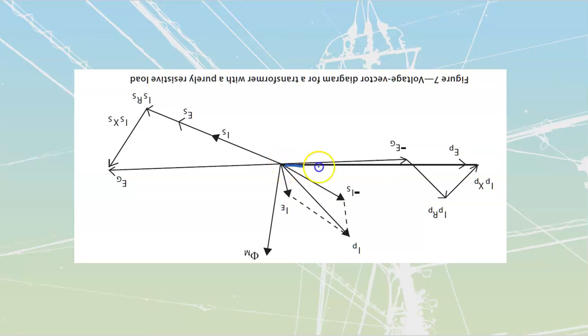And if we look all the way down over here, I'm going to see my applied voltage, which is this one over here. I'm going to see my secondary value of voltage. Now, they start drawing this one off the angle over here because they're starting to apply a bunch of other smaller drops that are going to be inside of here, IX and LS. But most importantly, what we see is we're going to have our secondary current, and then our primary current, which I'm drawing way off axis here as well.